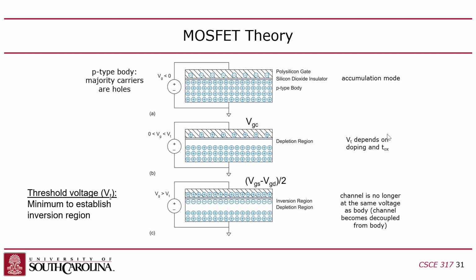Okay, so let's come back here to semiconductors. I mentioned that there's this kind of weird phenomenon that happens when you start charging the gate. Normally these transistors, if the gate is not charged up, are in a mode called accumulation mode. But as you start charging up the gate, it starts to push the majority carriers out.